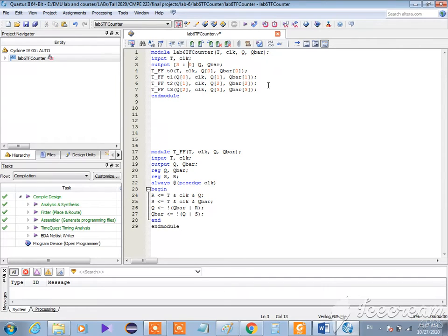Okay, so now everything is clear, because they are the inputs of our module. You can see how many inputs we have: 1, 2, 3, 4, and how many inputs we have in this module: 1, 2, 3, and 4. And this is the name of the module. We use the T flip-flop module. If this name is different, for example, if we name it EMU, this name must be the same. If we write EMU, here we should write EMU here.